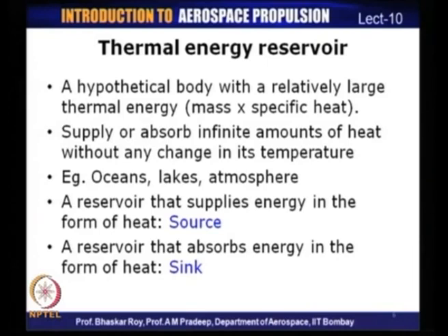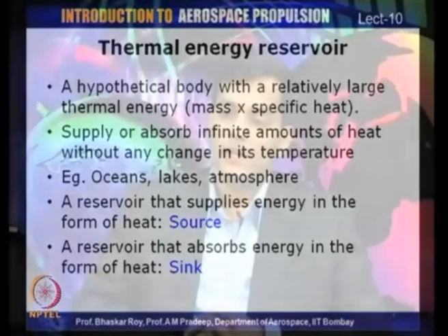We shall now look at what is known as a thermal energy reservoir. In order that we discuss more about the second law of thermodynamics and different systems like heat engines, etc., we need to understand what is meant by a thermal energy reservoir. A thermal energy reservoir is a hypothetical body with a relatively large thermal energy. Thermal energy here means the mass multiplied by the specific heat of that particular body. So, by definition, a thermal energy reservoir should be able to supply or absorb infinite amounts of energy in the form of heat or work without any changes in its temperature.